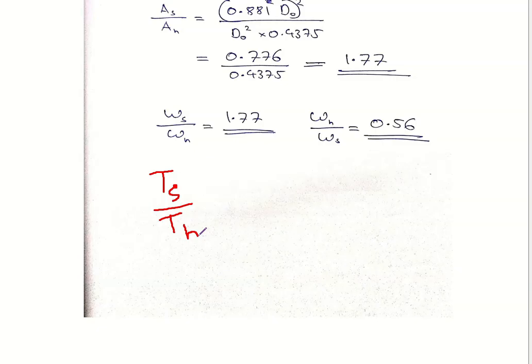But if they ask the resistance to twisting moment, compare the resistance offered by one shaft with the resistance offered by another shaft, then they are actually asking you to find the ratio of twisting moments only.